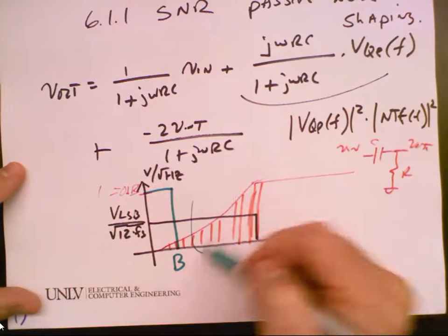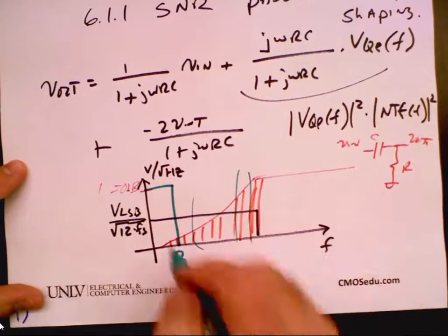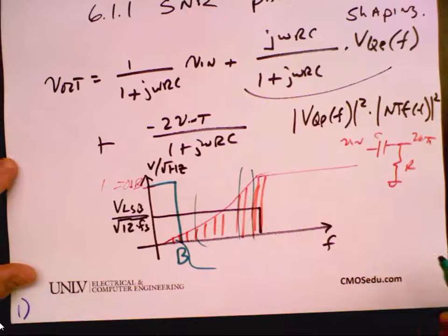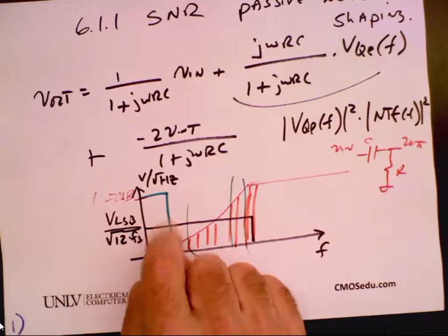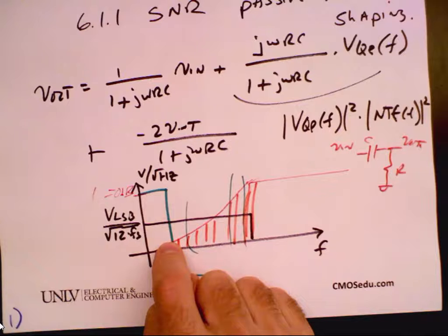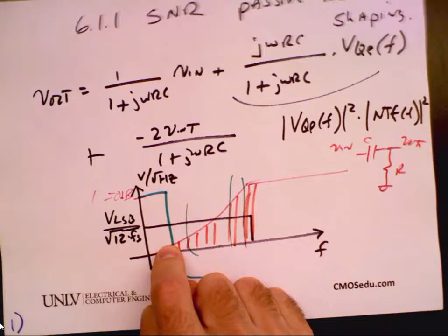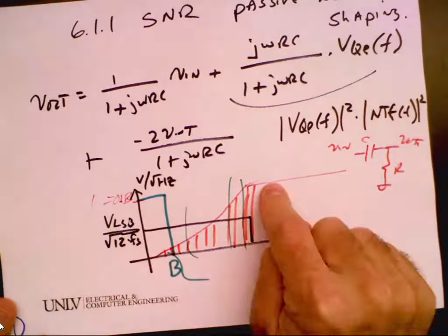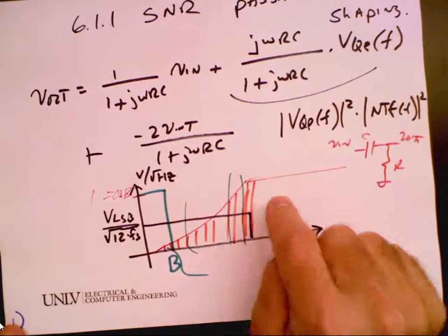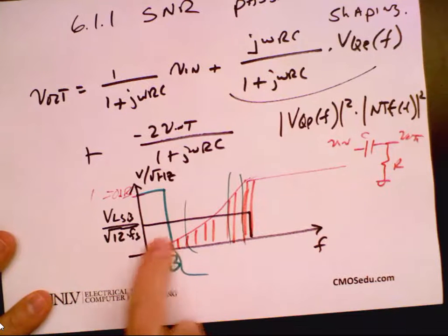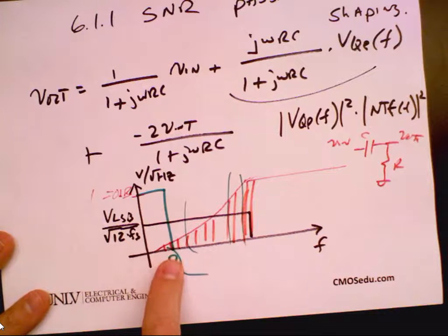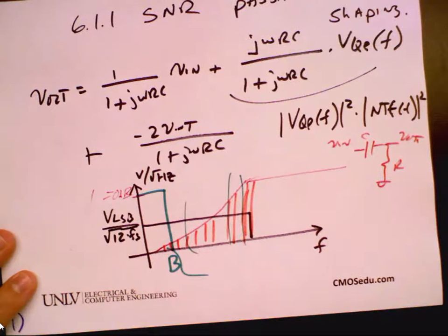And so I'm removing all of this quantization noise, and the only thing that's left is the quantization noise down here. Now remember in my example what I showed, this was the clipboard, and I was averaging the number of points, and we said that using noise shaping doesn't reduce quantization noise, it simply pushes it to higher frequencies, hence the name, okay? So here I remove the high frequency quantization noise, and what's left is the RMS noise right here in the spectrum. And so next I'm going to calculate this. Any questions? Okay, so I go back.